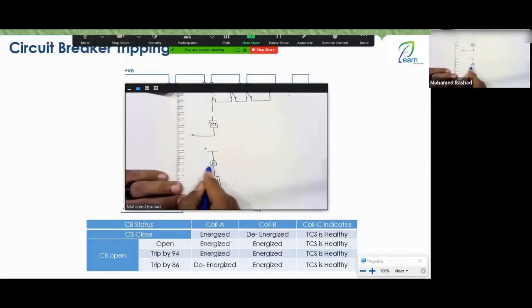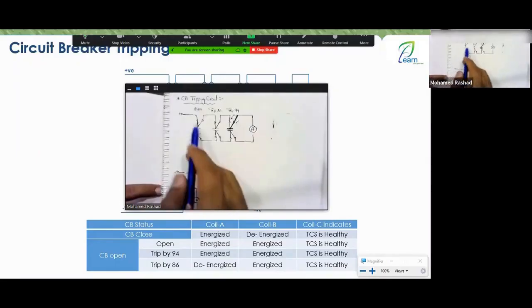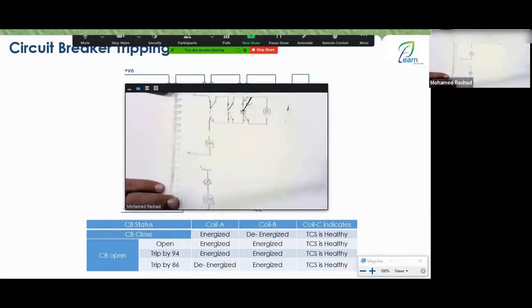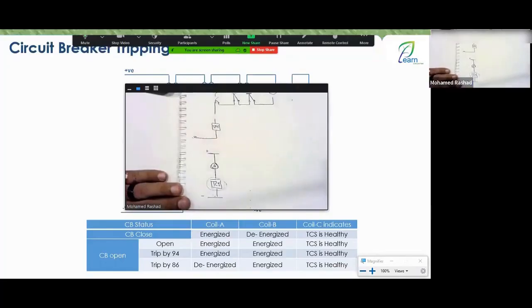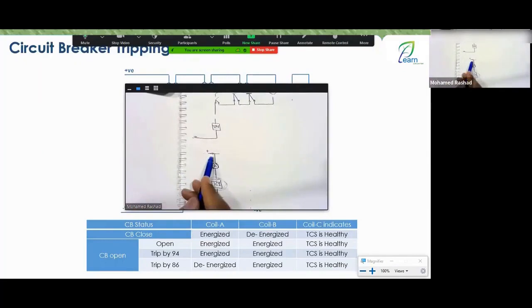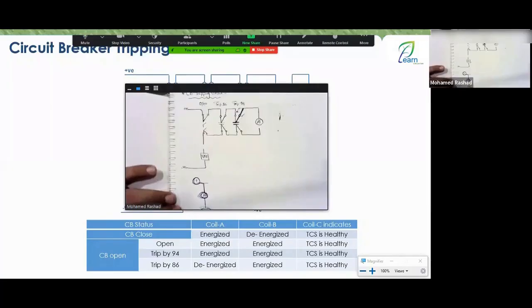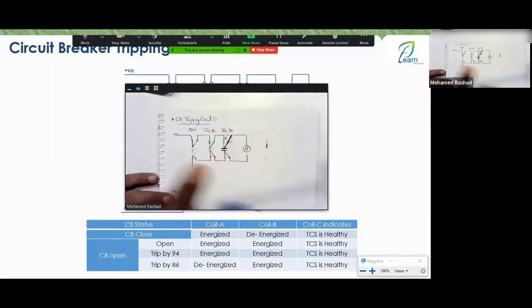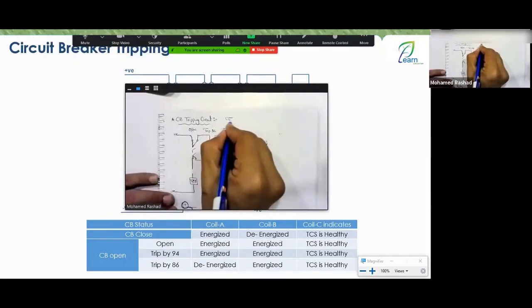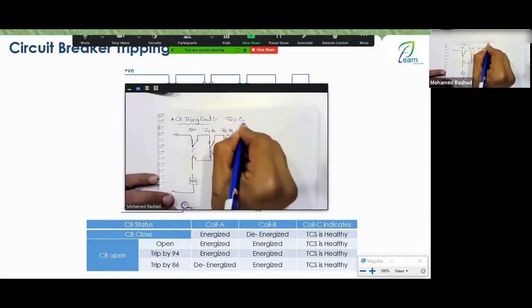So which coil is this? It monitors all the wiring you have in the positive direction and also monitors the negative, but through what? Through the trip coil. So it monitors everything like this. Oh, sorry. It monitors all the wires up to the contact and monitors the positive itself and the negative itself and monitors the wires from the negative direction and also monitors the trip coil. That's why in this case it's referred to here not as DC supervision, but it's called a trip circuit supervision.